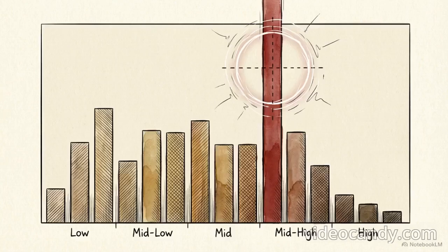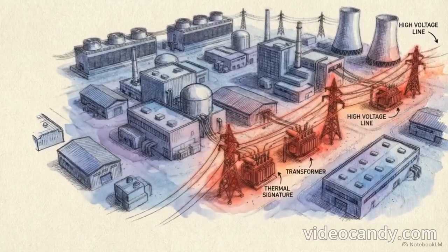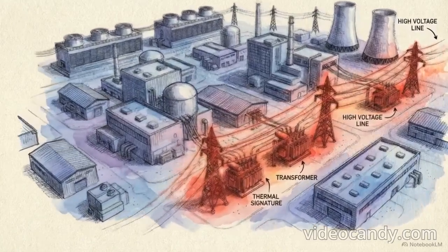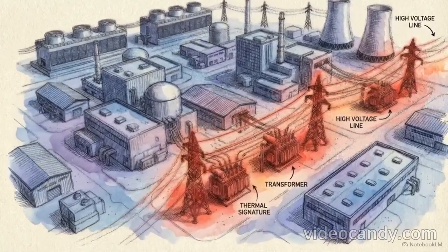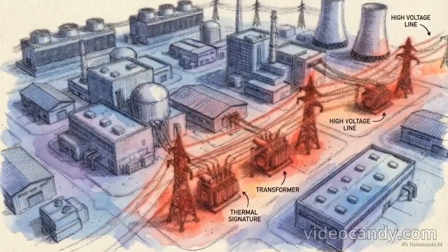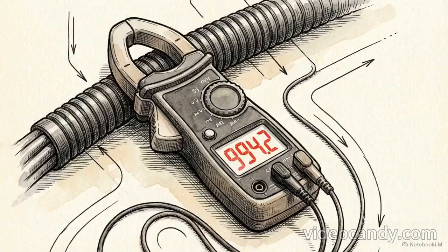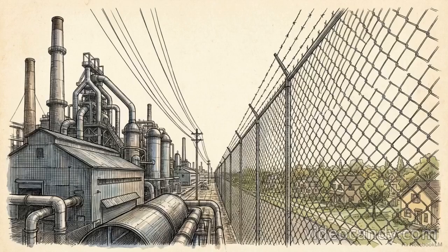If the facility utilizes power factor correction capacitors, the situation can escalate into harmonic resonance. The system's inductive and capacitive reactances can align to amplify specific harmonic frequencies, multiplying the current far beyond the hardware's rated limits. Harmonic distortion imposes a constant thermal burden on the system, bleeding efficiency through heat waste while degrading the physical reliability of all connected infrastructure.